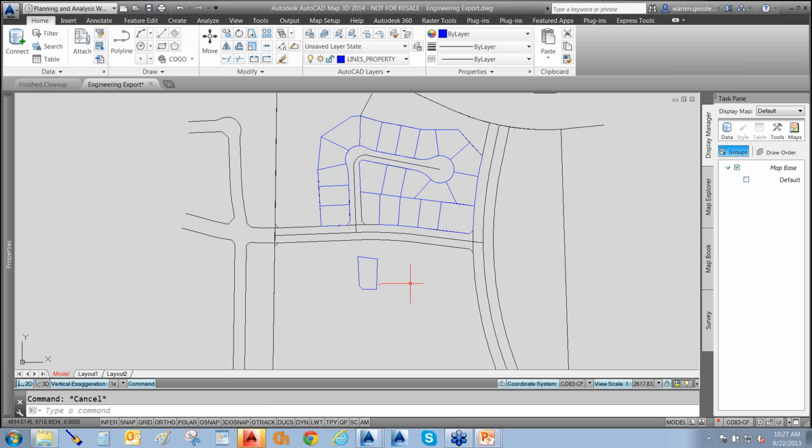This is a real cool, easy, fast AutoCAD command. Just bang, bang, bang. They're all in a proper layer. They're all the right information. So you see, just using AutoCAD commands, I can take a civil engineering project. What about those storm lines that had 2 lines instead of 1? Okay, just use an AutoCAD line command, connect the dots, get rid of the other ones. Just simple, easy stuff. Cleaning this up shouldn't take that long. Cleaning up your projects really shouldn't take that long, especially once you've got a system set up.